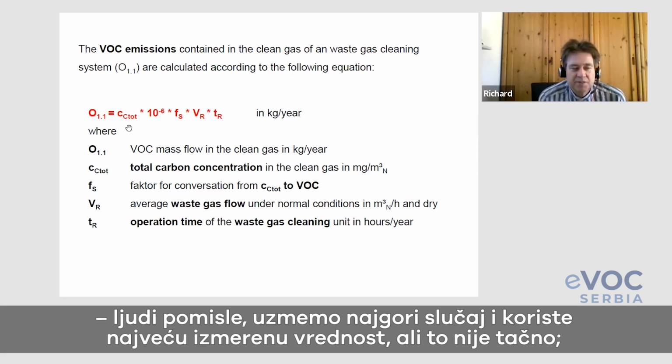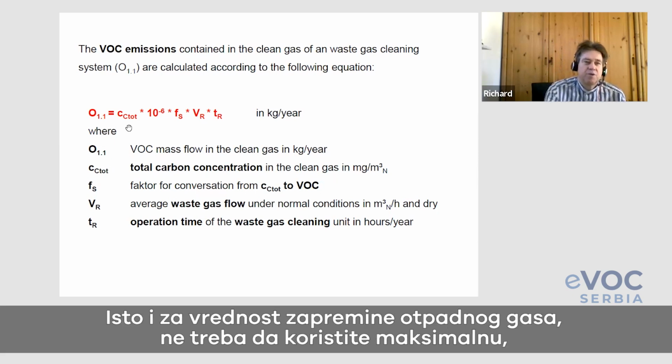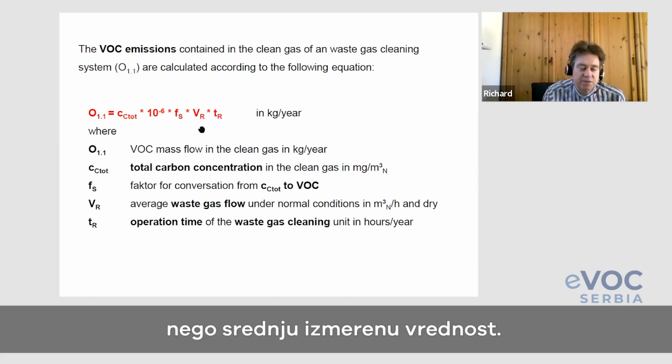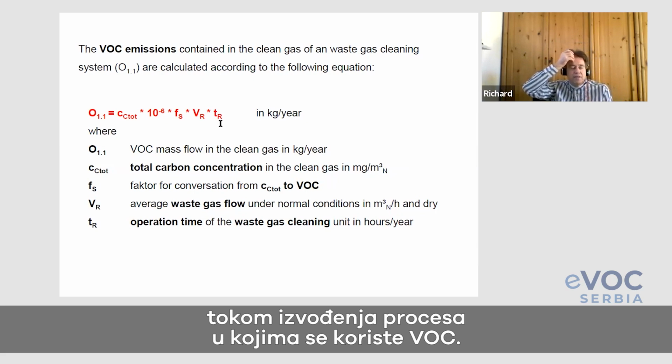Here, maybe some people are thinking, oh, we take the worst case, and so they use the maximum measured value, but that's not correct. You should use the medium measured value, and the same here for the waste gas volume. You should not use the maximum measured waste gas volume, you should use the medium value. And here it's very important, you need the operation time of the waste gas cleaning during the VOC